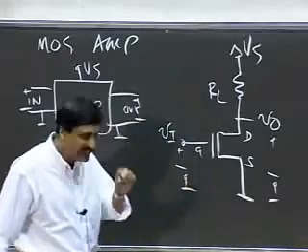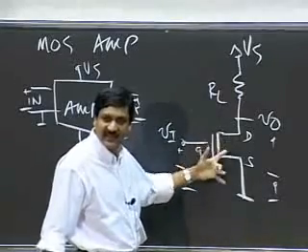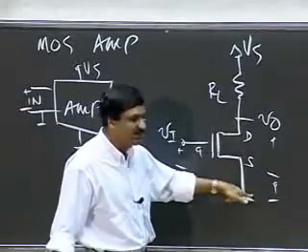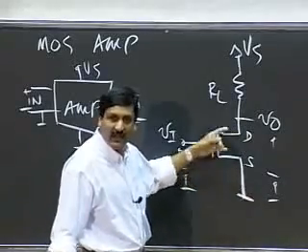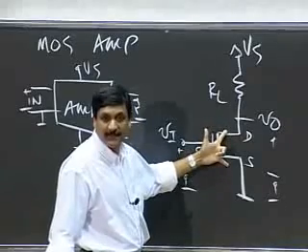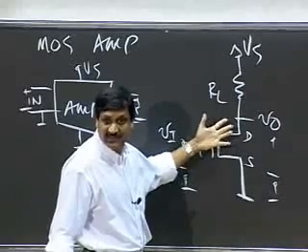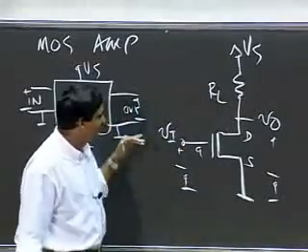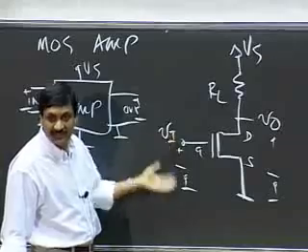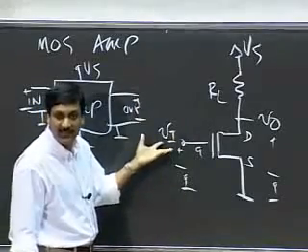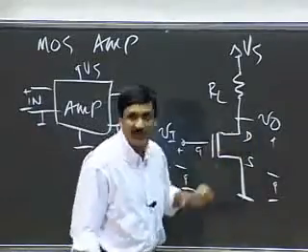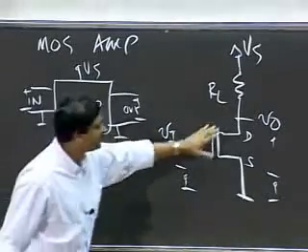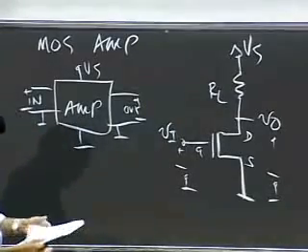When VDS is small, as in the digital designs where the MOSFET was on and pulled the voltage down to ground, we could view this behavior as a resistor. It is actually the same thing. It is an amplifier, and with digital designs, I was driving it with 5 volts and 0 volts, rail to rail. As an amplifier, what I'm doing now is looking at a small region of its behavior when VDS is greater than VGS minus VT.